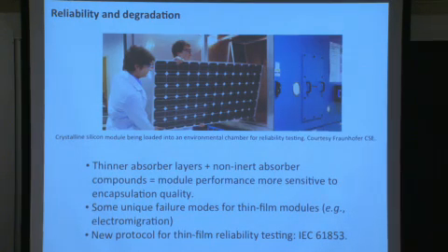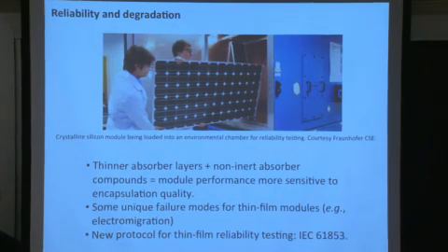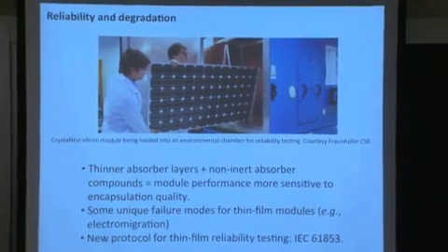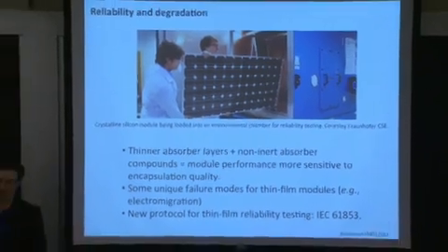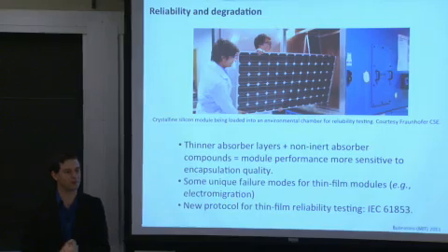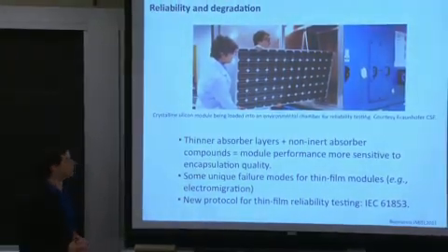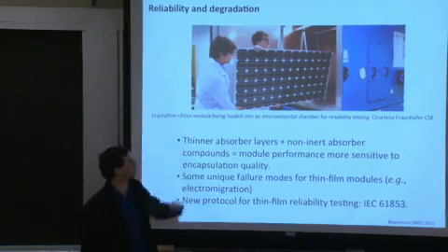And then the temperature can drop down to as low as minus 40 degrees C, depending on what the environmental chamber is designed to do, exactly how it's designed to stress or test your module. And the idea is to promote an accelerated degradation of the module on purpose to test what its failure modes will be. And we'll see these when we take the tour of Fraunhofer CSE in a couple of weeks. This is a crystalline silicon module being loaded in.